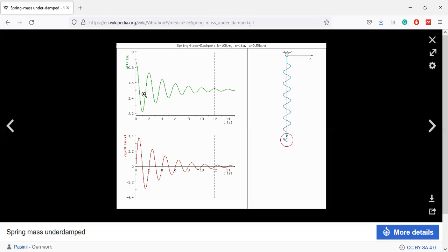Okay. So there is also a logarithmic decline in every cycle. For example, from here to here we have one cycle, the second cycle, the third cycle. So in every cycle, there will be a constant logarithmic decline of amplitude. If I consider this as x1, this as x2, then x2 over x1 is calculated. So that is part of